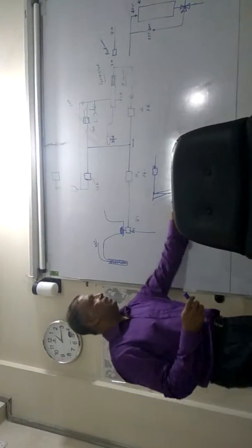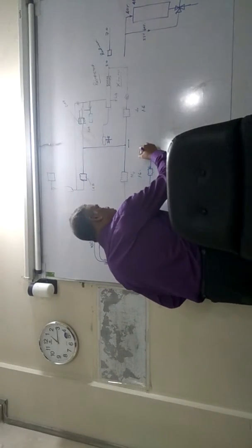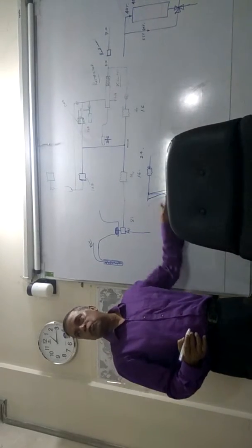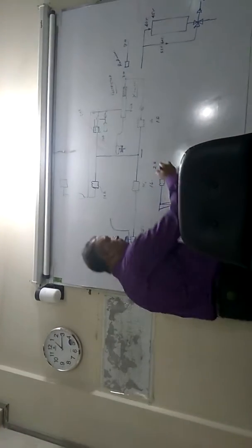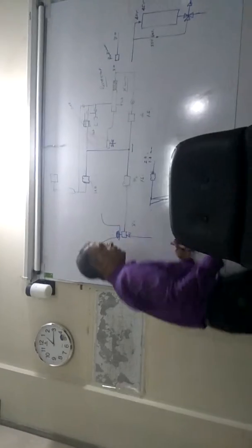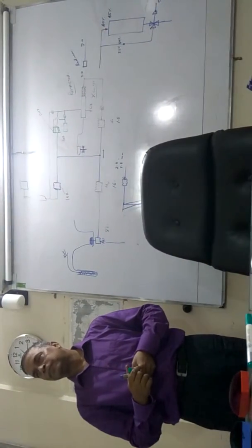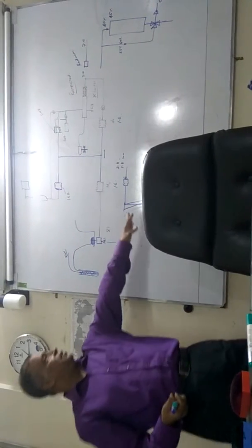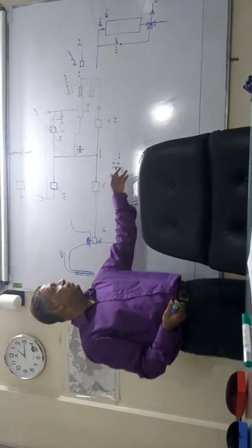So earlier, due to the temperature change, our pressure had become 2.0; now it cannot be 2.0. It is so far away from there, right? Possibly this time the pressure will be 1.8. Agreed? Controller output will be, instead of 2 bar, maybe because of this proportional action, now 1.8.